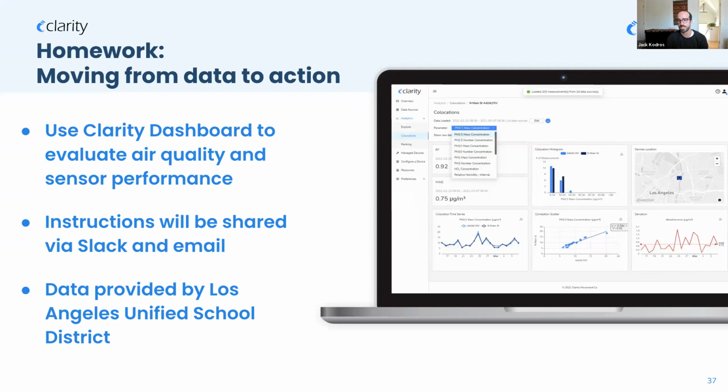There's no one specific answer for how large an area one sensor can measure. It comes down to the type of pollutant and the sources. If you have a lot of different sources in one area, you need more sensors. If you have fewer sources, perhaps you're in a more regional area and you need fewer sensors. It really depends on the project, and thinking about that's a really important step for setting up an air quality monitoring network. Great answer, Jack.